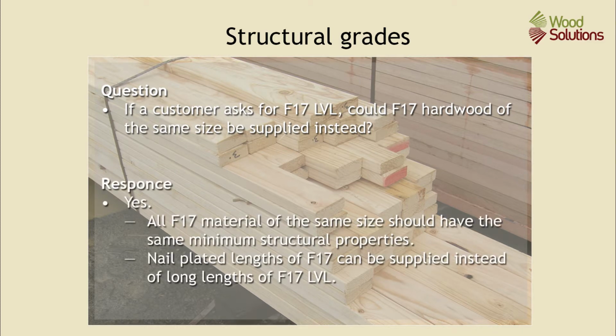Yes, it can. All F17 material of the same size should have the same minimum structural properties. Also, nail-plated lengths of F17 can be supplied instead of long lengths of F17 LVL.